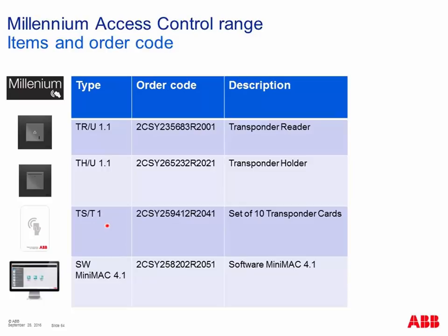Sometimes on the market, especially the cheapest ones that you can find maybe on some website on the Chinese market, there are MIFARE cards that are declared as standard, as compliant to MIFARE, but sometimes have some emulation and so they are not completely compliant to MIFARE. So in this case, the interfacing could not be guaranteed. But theoretically speaking, every standard MIFARE card can be used for this solution.